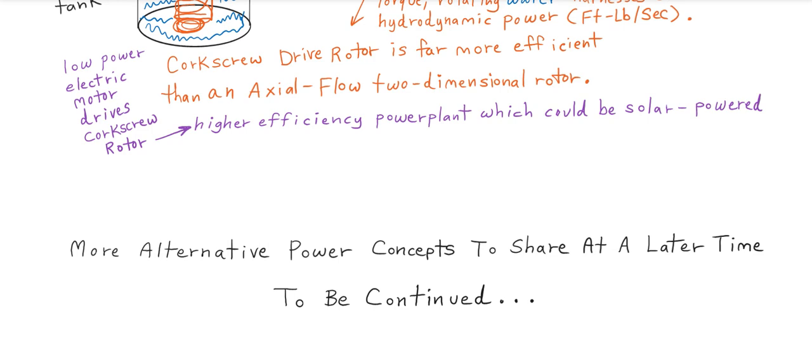Another design challenge with the valve train for compressed hydrogen, or for combustion of hydrogen gas, is that due to the molar mass of hydrogen being so low, it's almost impossible to develop a valve train that will consistently seal the hydrogen gas in the combustion chamber of the reciprocating engine. Unless material science is already advancing exponentially, more than likely you couldn't do it with a poppet valve system that actuates, not for any long-term reliability. Maybe safety, yes, but reliability, no. So it's a safe engine, but then you go out of business because nobody wants to buy the product. It's junk, right? So reliability is probably a no-go for combusting hydrogen inside a valve train system.